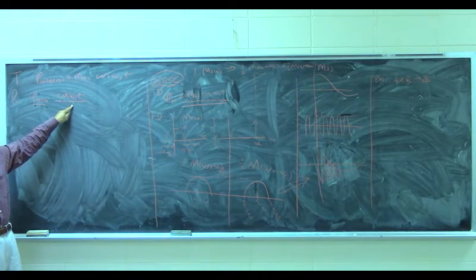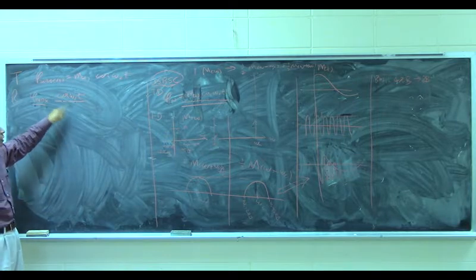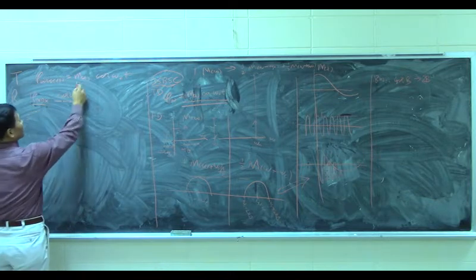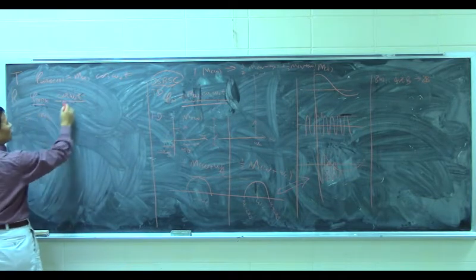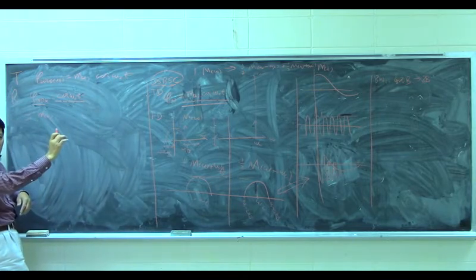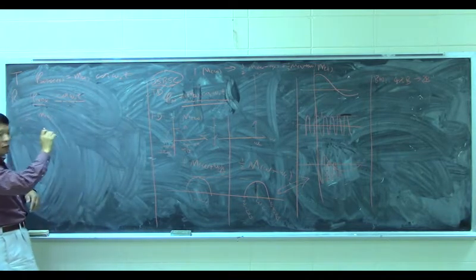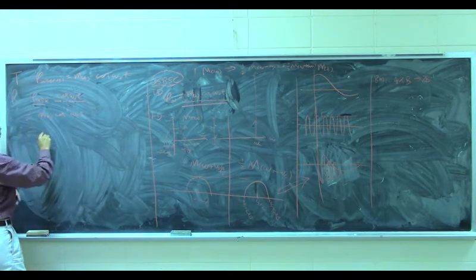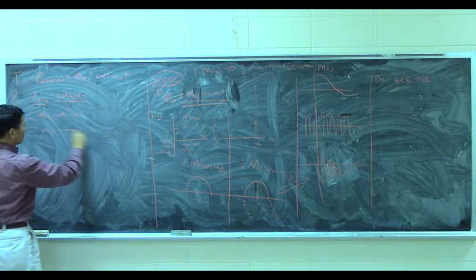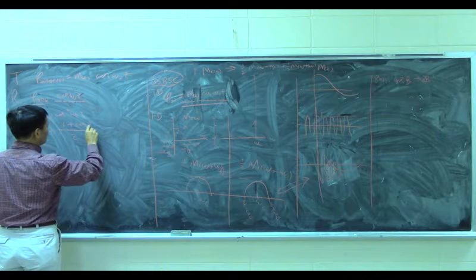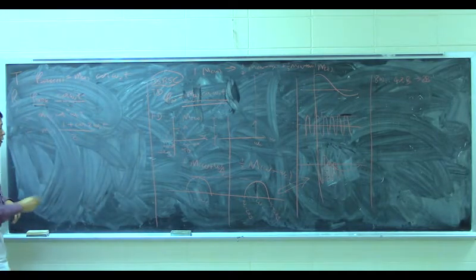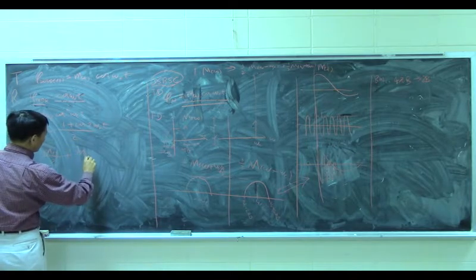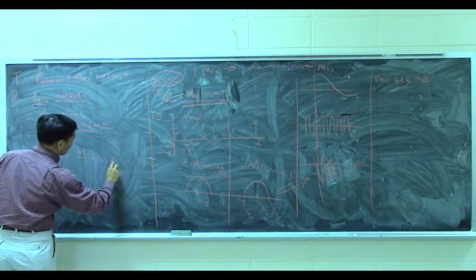It is clear. You know what we are doing, right? You multiply this again. Okay, now from math, let's see what happened. So this one we know is this: m(t) times cosine omega_c t, times cosine omega_c t again. So that is cosine squared omega_c t. Now from trigonometry, cosine squared equals half of 1 plus cosine 2 omega_c t. Now this one will equal m(t)/2 plus m(t)/2 times cosine 2 omega_c t.